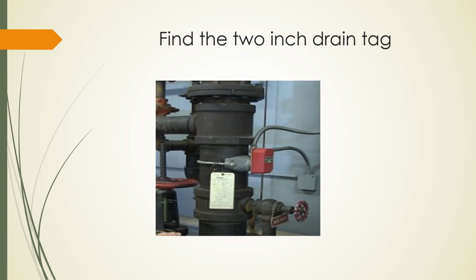There'll be 2 sets of numbers. There'll be a higher number and a lower number. 95, 85, 75, 45, whatever, but there'll be 2 sets of numbers. The higher set's the no flow, and the lower pressures is the flow situation. And we're going to use those 2 numbers as the basis for our water supply test.